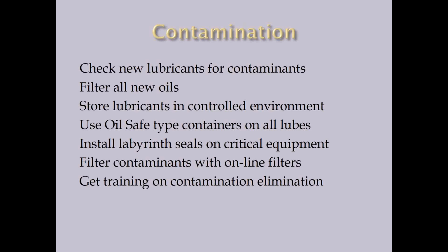So in contamination, check your new lubricants for contamination. Filter all your new oils. Store your lubricants in a controlled environment if you can. Use these oil-safe containers, but they're not good to use until you get your lubricants really clean. Otherwise, you're just taking dirty lubricants around, but they are much better than Tide and Downy jugs. When you order new equipment, get Labyrinth seals put on your critical equipment to keep particles, dust, and moisture out. Use these online filters, filter carts.